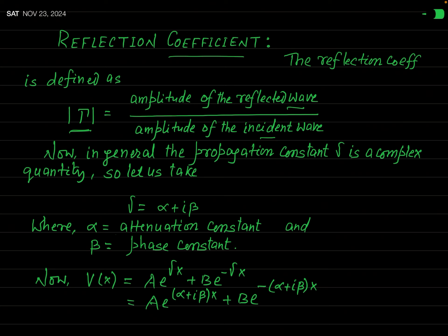In case of a light wave incident on a surface, it depends on the nature of the surface. Similarly, here the load end behaves like a reflecting surface, and how much voltage or current will be reflected and move in the opposite direction is measured in terms of this reflection coefficient.